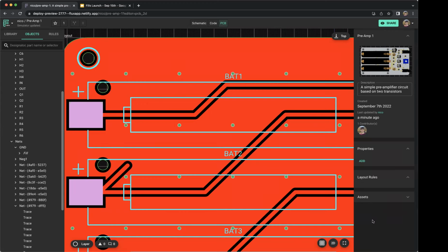I've done that, but with the fields and the signals, the potential to cause problems between ground splits is huge. I always tell my newer engineers, just do one big ground. Just tie the whole thing. If you want to do something like that, you need to have a really good reason to split a ground.